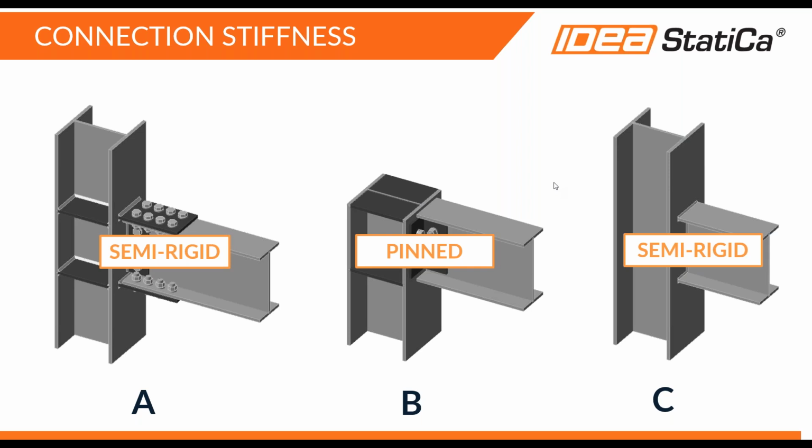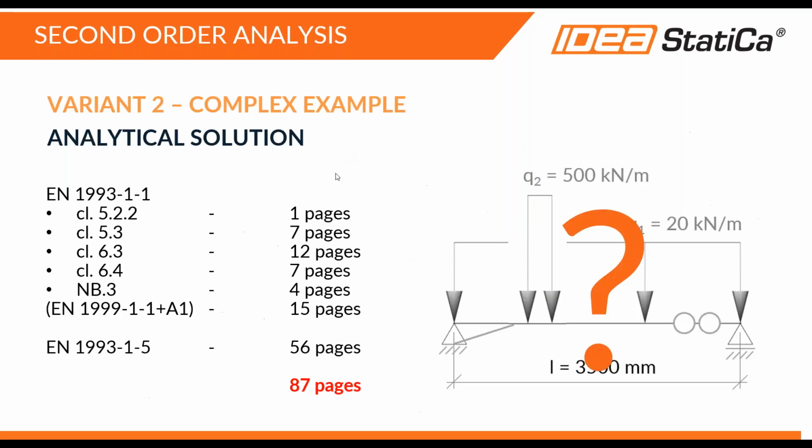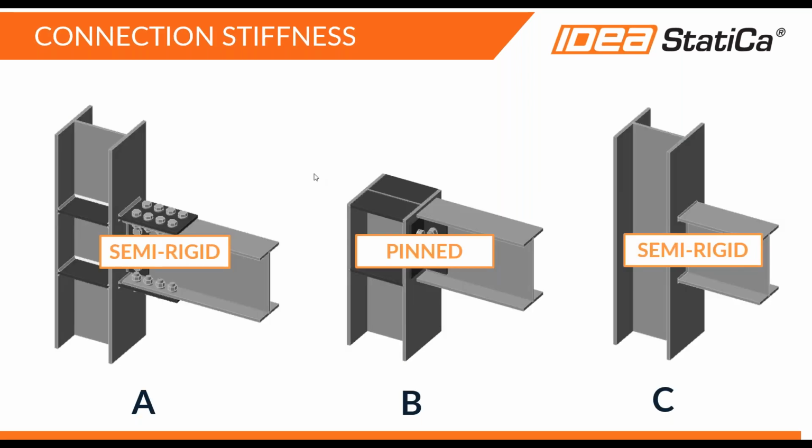So I wanted to share this with you, because this is a very important fact for the hand calculations, where we have to determine the stiffness of the supports for the beam, right? Because we need this to choose the correct row or the correct parameters from the table.